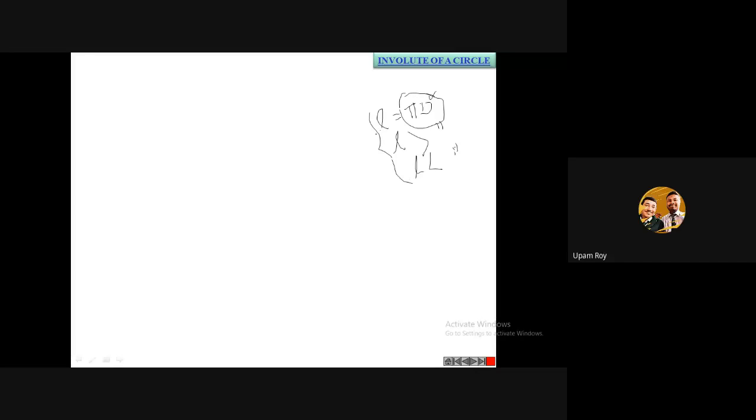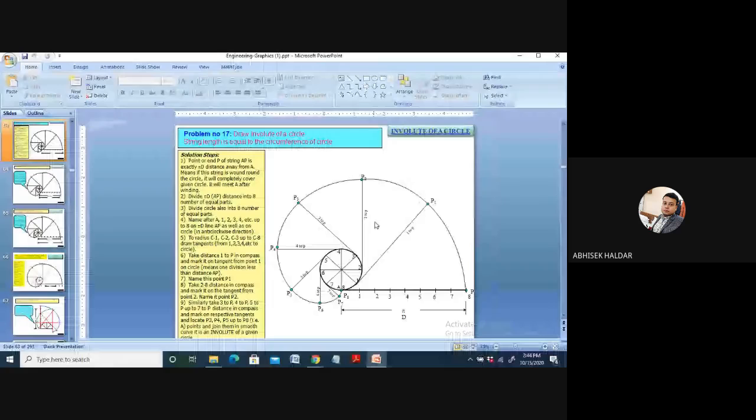Yes, sir. Pi d is the main calculation you have to do, as the diameter of the cylinder will be given, and the length of the string that you have to wind around the cylinder or disc will be given. So you can easily check which case you have. But the process is the same. The drawing of the involute is the same. So let us see now how to draw the involute, taking a particular example. Let us start with the first one, when my string length is equal to the circumference of the circle.